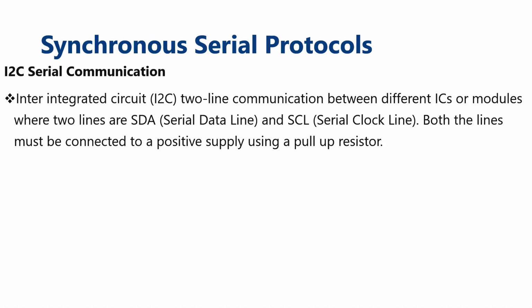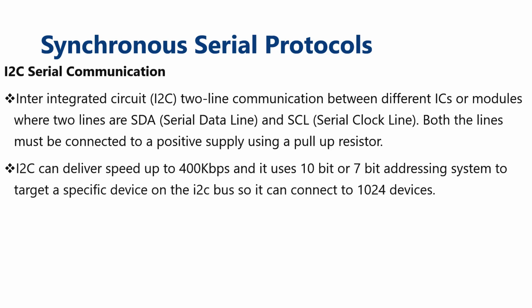Inter-Integrated Circuit, I2C, is a two-line communication protocol between different ICs or modules, where the two lines are SDA, the serial data line, and SCL, the serial clock line. Both lines must be connected to a positive supply using a pull-up resistor.